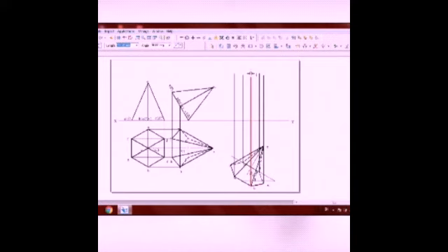The base axis line you draw at the end, otherwise it will be confusing. That line is already coinciding with the apex. Now draw the horizontal lines from A dash, B dash, etc. Of course, from there it is the XY line itself. Now think of joining the lines starting from A. That is, you are now constructing the base portion of the final front view.